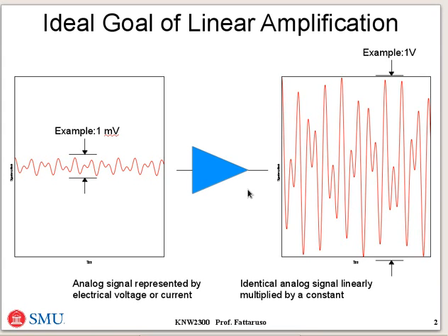And so in this example case, this amplifier has enough voltage gain through it to boost the level of this input signal up to where now the output level is varying about a volt peak to peak. So this is an example of an amplifier with a voltage gain factor of about 1,000. And this is ideally what we would like. We'd like a circuit block that basically does a linear multiplication of the input signal times some constant gain factor to give an amplified output signal.